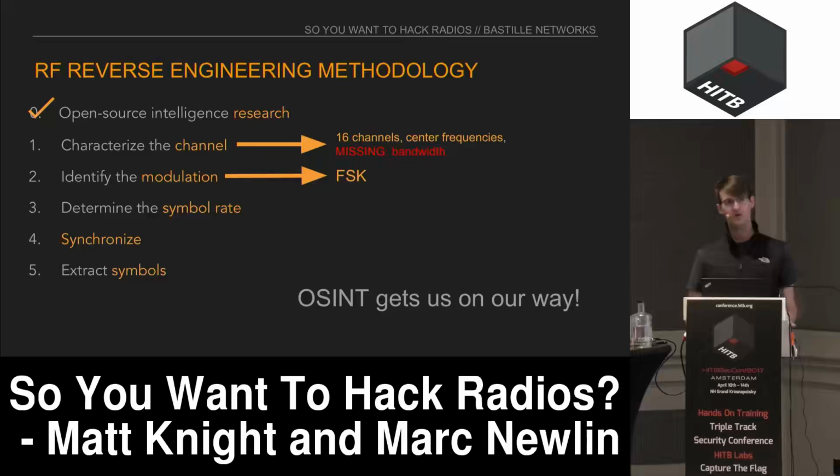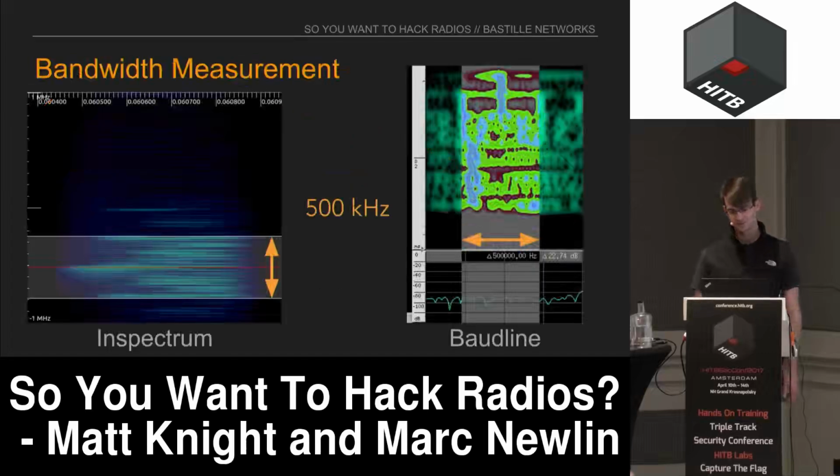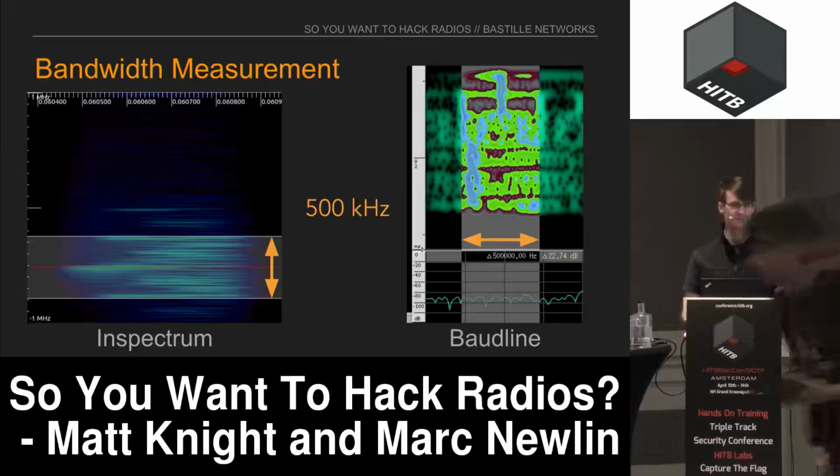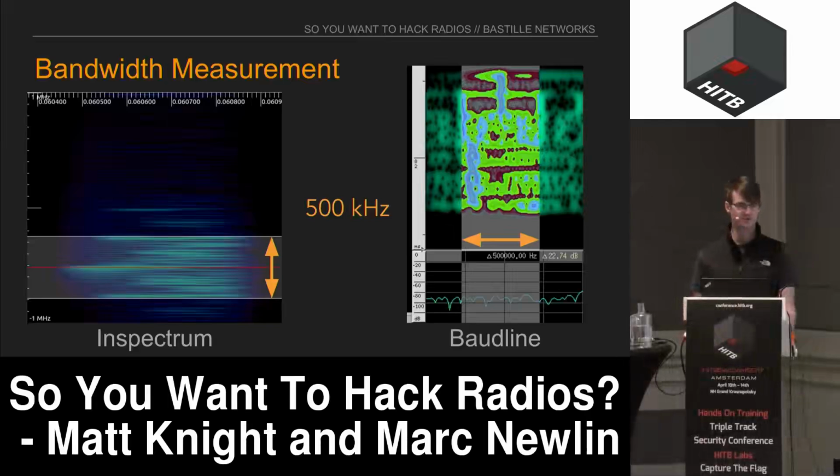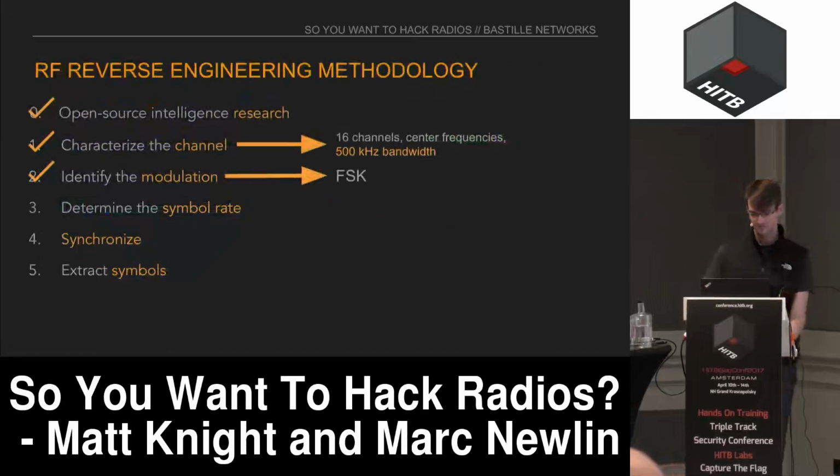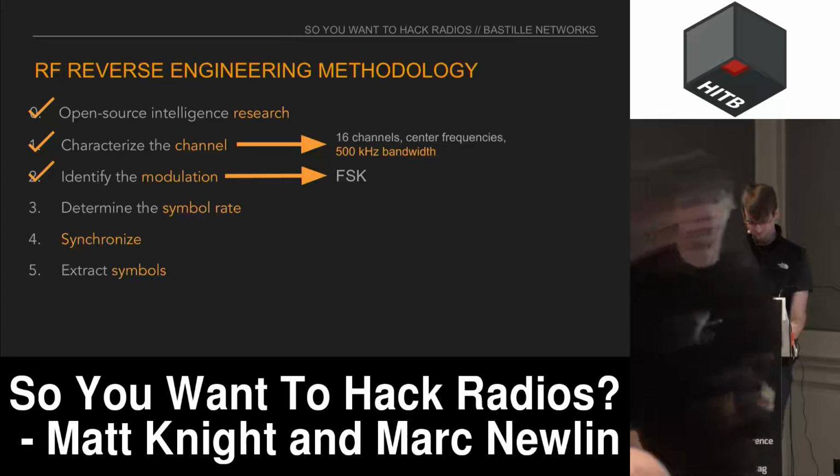So one thing that we were not able to recover in this process, the last step in characterizing the channel, is the bandwidth, right? So we can measure this empirically using our software-defined radio and our device. If we generate some traffic with the device, we can use any number of tools to measure the bandwidth here. You can use Baudline and Spectrum, two that I really like. They're both spectrum visualization tools. You basically can just load up your capture and then use the cursors built into both to measure the width of the channel. And then we can discover the channel is 500 kilohertz wide. So having discovered that, we've now fully characterized the channel and have identified the modulation. So steps 1 and 2 are done.